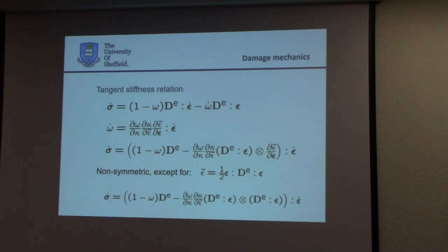Now you have to do a little bit more usually, and that is related to the fact that you not only have to compute your stresses from your strains, you also have to compute the displacements. In nonlinear processes, you always have a double loop. You have a global equilibrium loop to update your displacements.